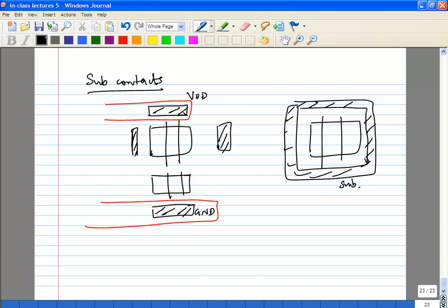So what does the substrate contact do? If you have, let's say, a switching transistor, so you give it an inverter and then you give it a clock signal, the substrate will always have some impedance, some inductance or whatever. So definitely your substrate will be wiggling. So what effectively is happening is your noisy transistor is injecting something into the substrate.